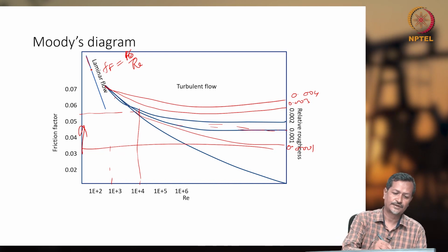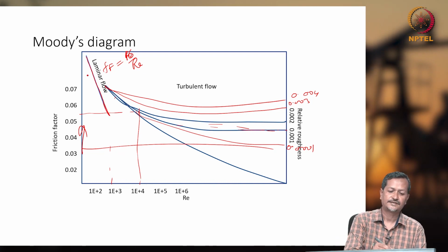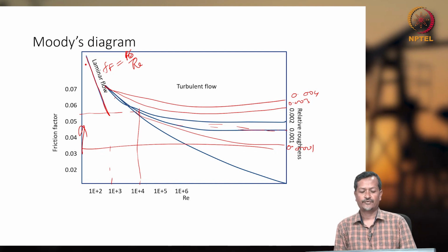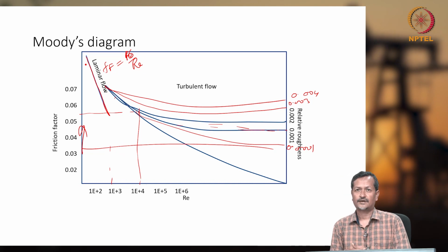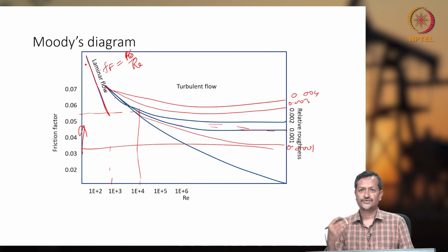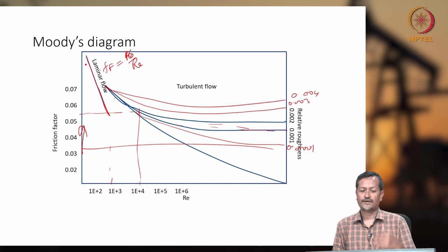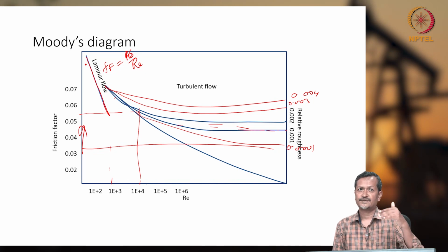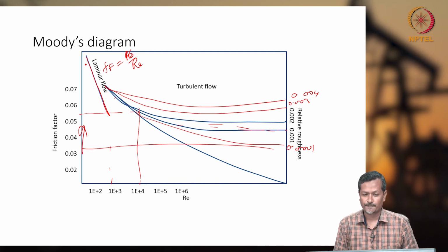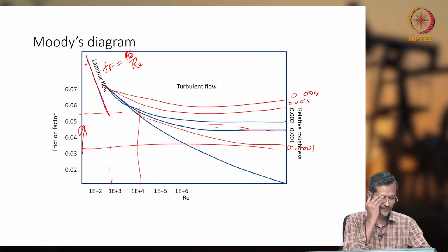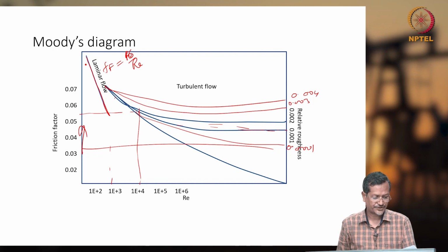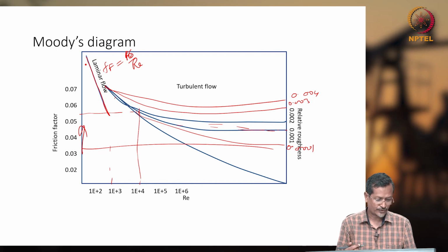This chart has one straight line, called the laminar flow region. But if your Reynolds number increases, then you reach the turbulent flow region. In that case you have to check the relative roughness, and roughness will give the friction factor. Higher roughness implies higher friction factor or higher pressure drop. So from this chart we got the roughness value, and the Moody's friction factor we get is 0.0265.